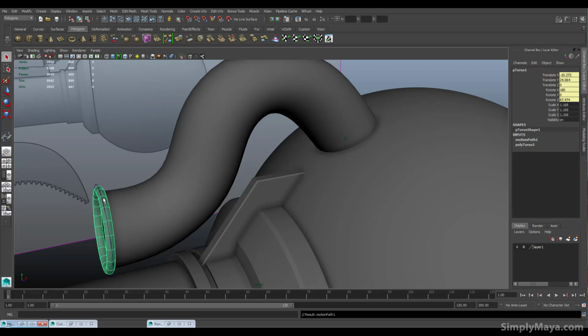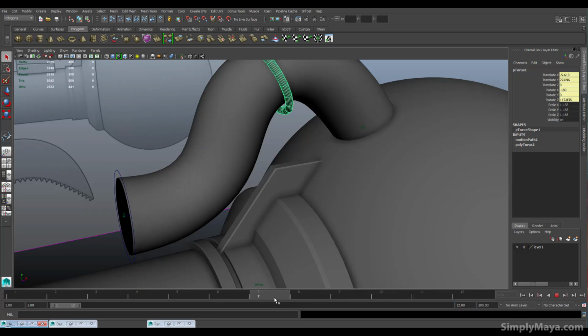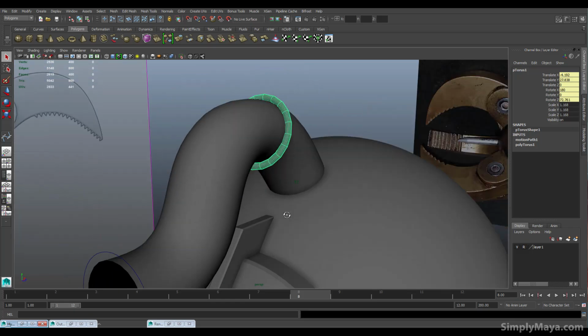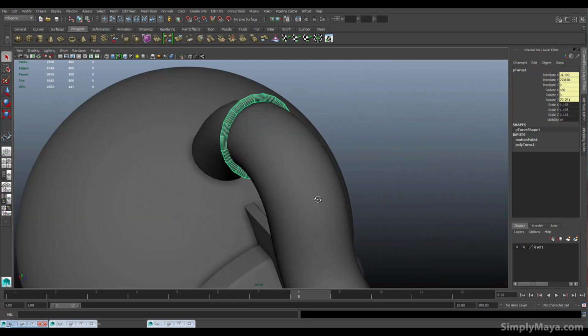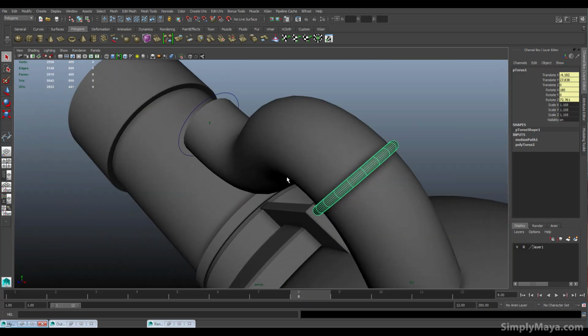Okay, and you'll see that's straightened up a bit. It's attached to the motion path. I'll change my frame range down here to 12, and you'll see that that's created 12 copies of this object all the way along our curve. Now they're not perfectly placed in some instances, and some of that would be to do with us moving those vertices before we did this. But you know, they're pretty close. It makes it a lot easier to edit.